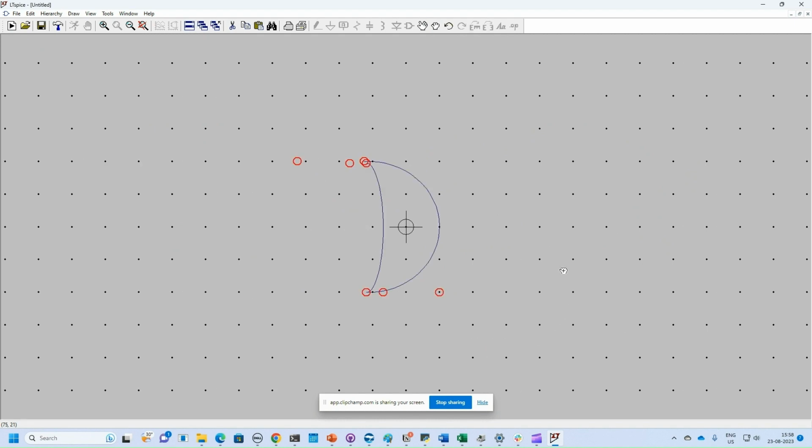The next thing that you need to do is to have lines. So go to draw, click on line, and then draw terminal lines. Let us say the NOR gate has two terminals. So here also you draw a terminal line. What you need next is a circle or a bubble to show that it's a NOR gate. So you have to go to draw, say circle, then you create a circle anywhere. Once you create the circle, press escape, and the circle is created. Now you can use this drag button to drag the circle and place it at the right end of the OR gate to create the NOR gate.